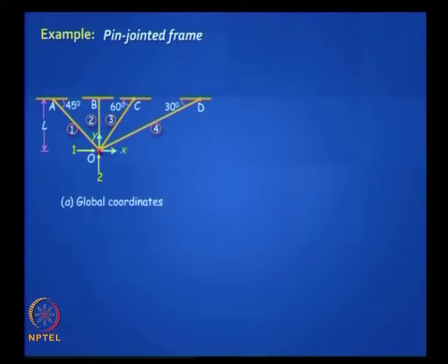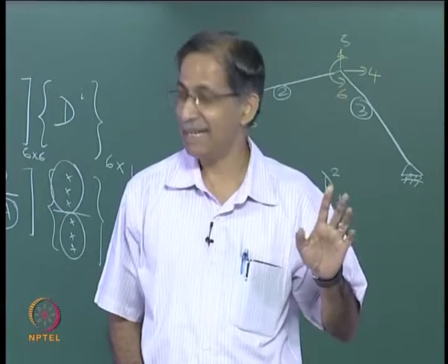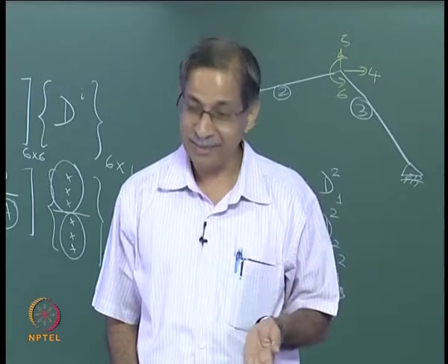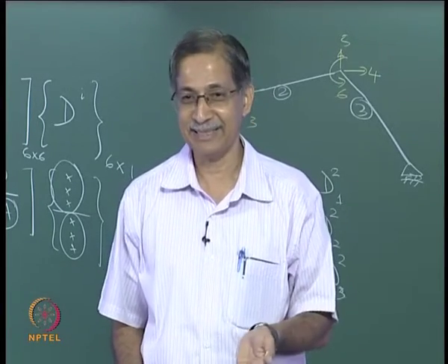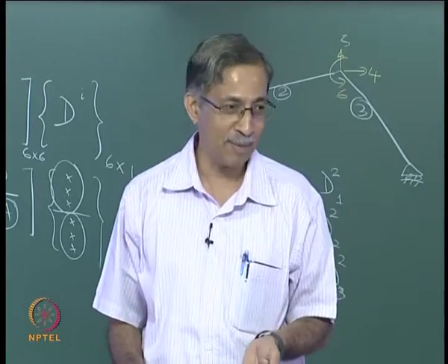Then how many restrained degrees of freedom do you have? 4, sir. Why do you say 4? Because it is along the member force acts. So for each member only one, at A1, B1, C1, D1. But he is strictly right in the sense you know the direction of your support reactions in this case, because they have to be aligned along the members in this particular problem.